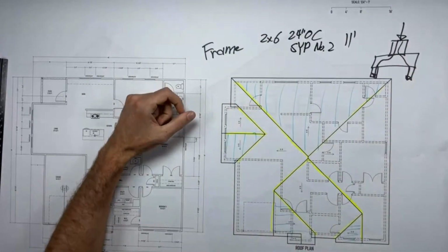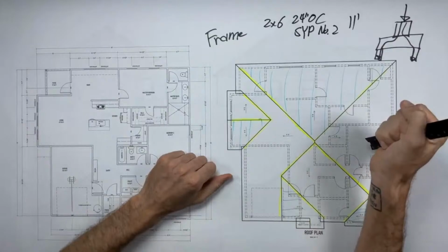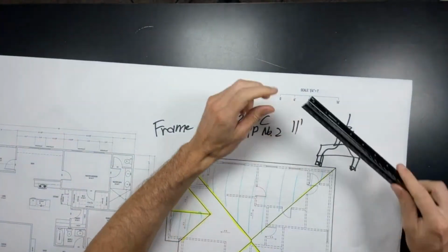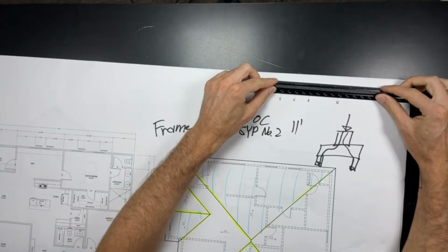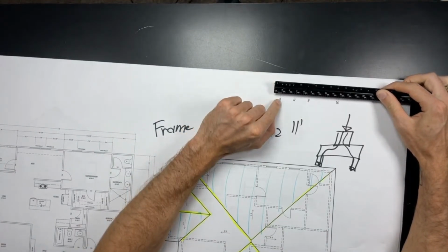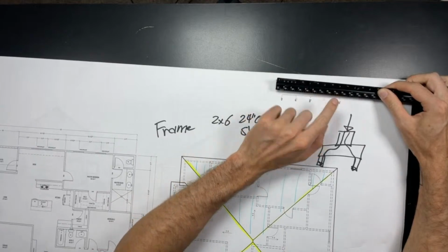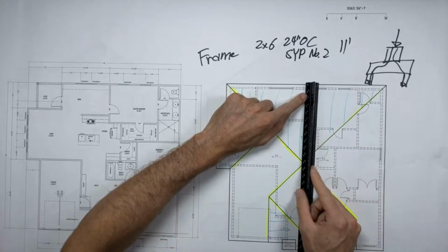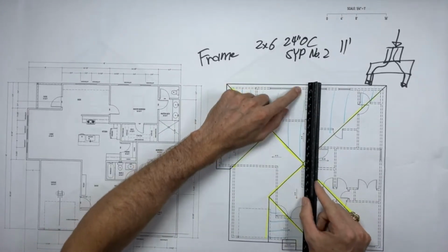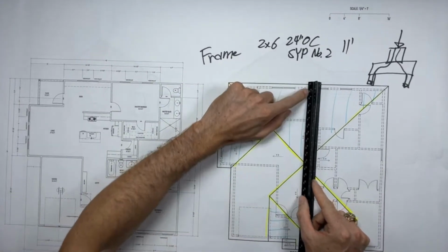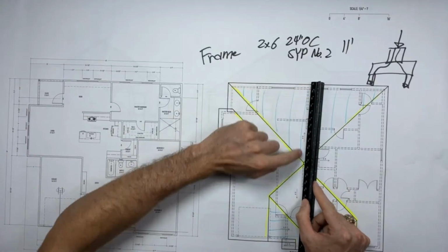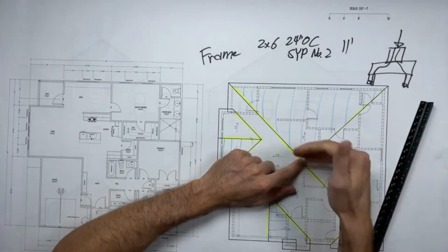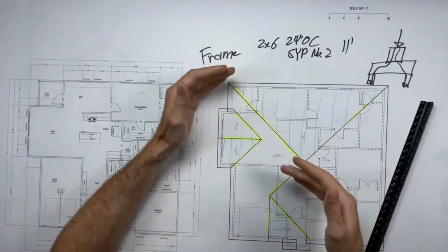Okay, so what we do is we take our magical scale and we find the 1/4 inch per foot spot, because these are printed 1/4 inch per foot. And look, here's a scale up here. And if I wanted to double check and I put the scale on it, I don't know if you can read this, probably not. But see how the 0 and the 4 and the 8 are lining up with these numbers? That means this is printed to that scale. So I can use this. All right. So I'm going to go from the 0, and I want to see, first of all, how long is my longest rafter? So from the inside support of the wall up to here is 20 feet. That's pretty convenient because that means I can split it in half, and I've got two 10-foot spans on the maximum, and I'm good to go.